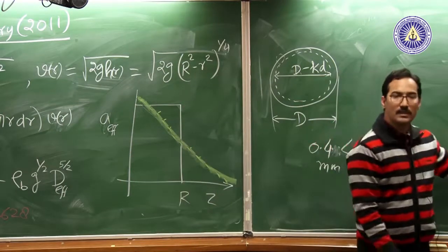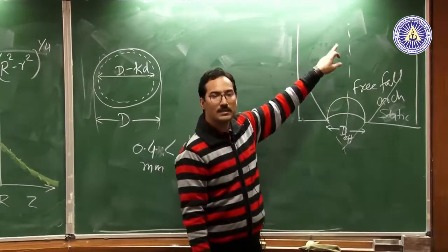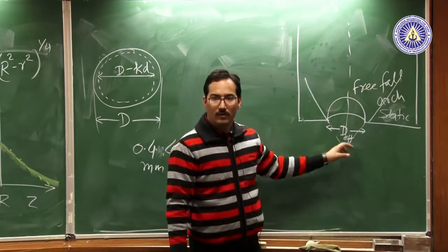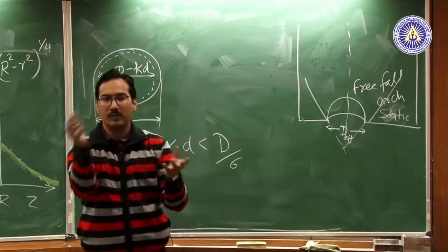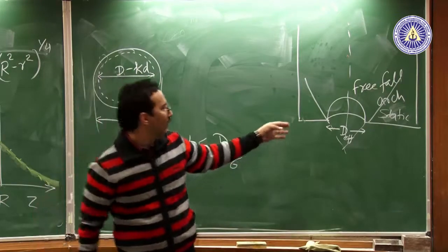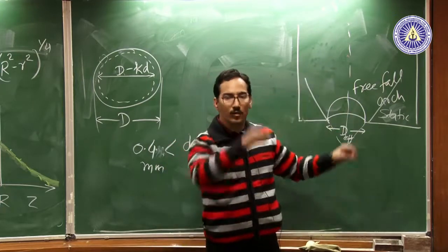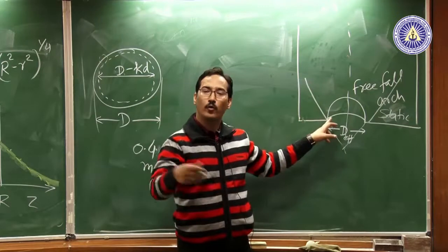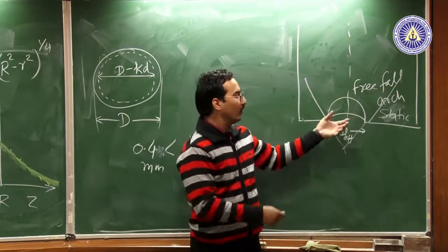But if you look at the collisional stress, you don't see that this is the region. The collisional stress would suggest that you have a continuous variation. If you are assuming a free fall arc, everything is falling under the influence of gravity, then you don't expect any significant collisional stress here. So what people say is that in that sense, you have a stress continuity. There is no stress discontinuity, and so the approach which people have tried is not going to work.